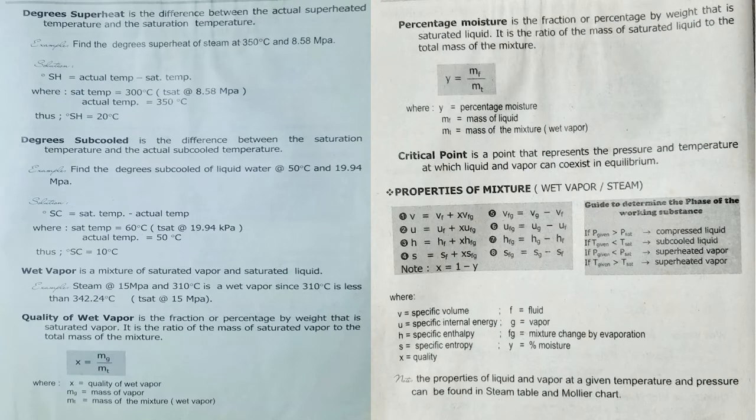Degrees superheat is the difference between the actual superheated temperature and the saturation temperature. Example: find the degrees superheat of steam at 350 degrees Celsius and 8.58 MPa. The solution: SH, or degree superheat, is the actual temperature minus the saturated temperature, where Tsat at 8.58 MPa is 300 degrees Celsius and the actual temperature is 350 degrees Celsius. Thus, degree SH